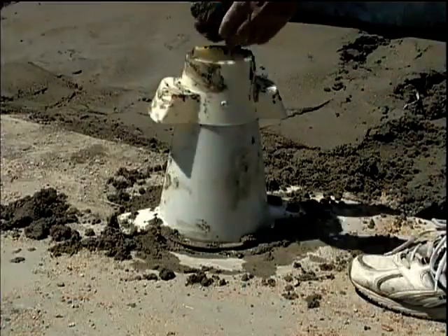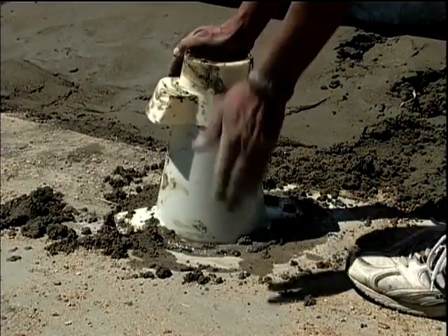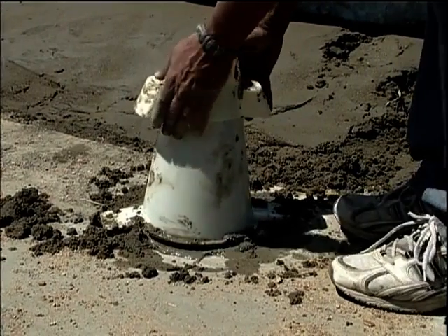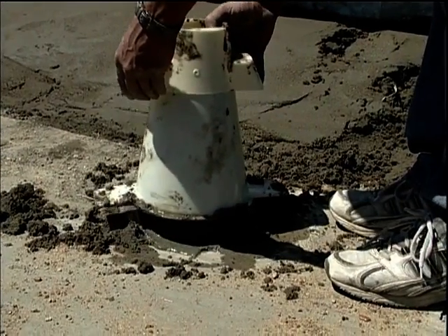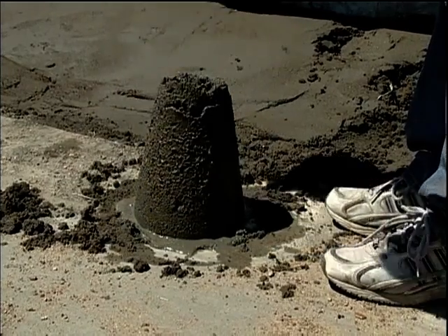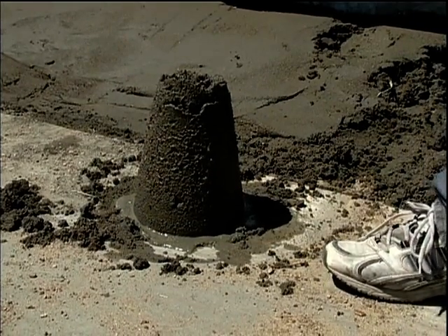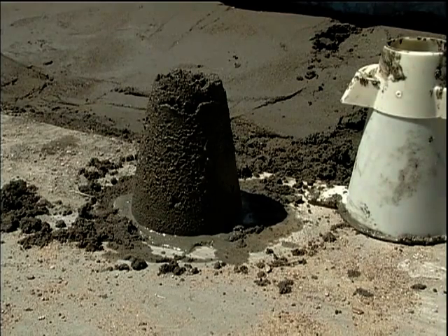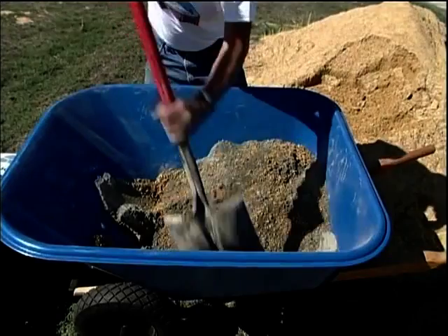Also, the water mix or ratio should be a dry mix. We suggest using a 3-inch slump. Concrete slump is the amount of water used to give the desired consistency. A slump cone is available to test the slump. When using a 3-inch slump, the mix will be about as dry as you can make it without it setting too quickly. We suggest 2 ways to mix the slurry.